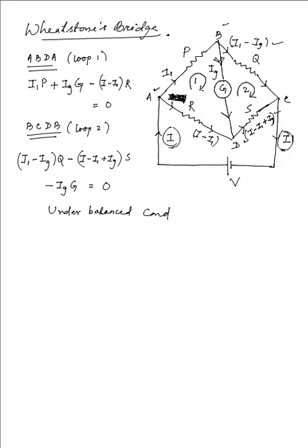what we have is that the galvanometer must not show any deflection, which means the load is equally balanced on either side, or we can say the potential difference remains the same between the points B and D, or there is in fact no potential difference between the points B and D. So there will be no current flowing across the galvanometer, and hence it will show no deflection.